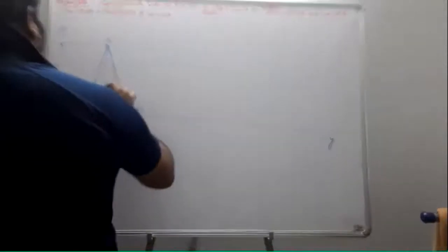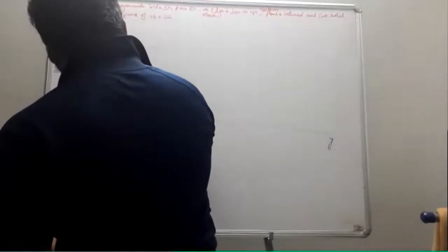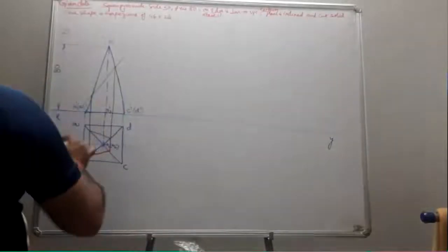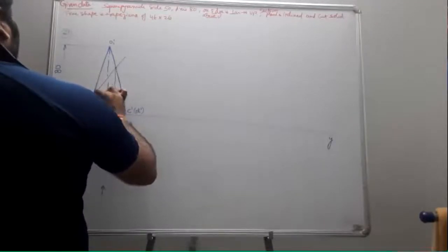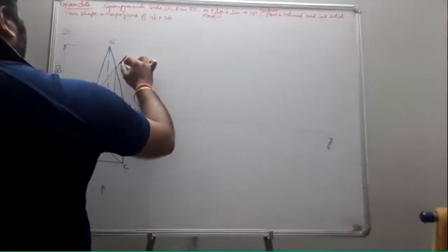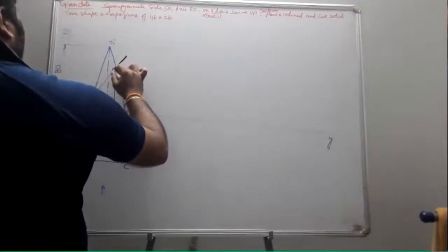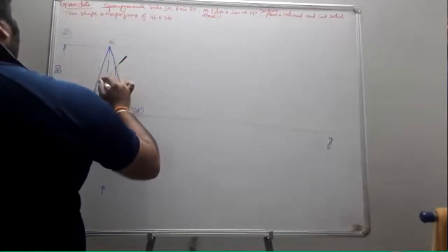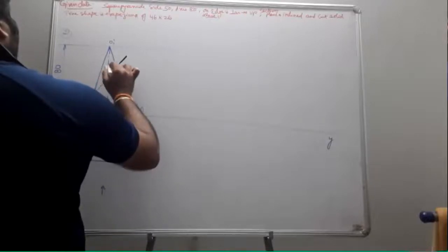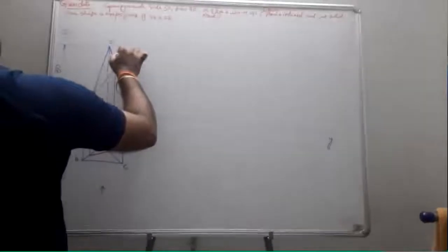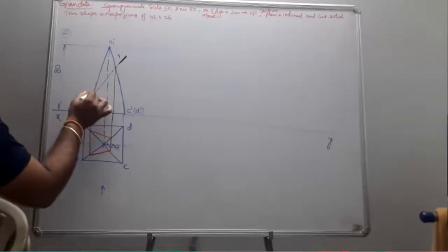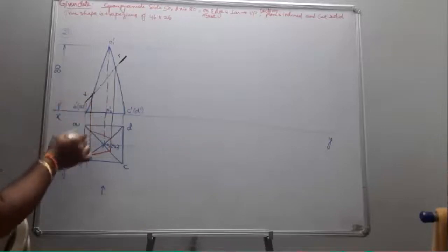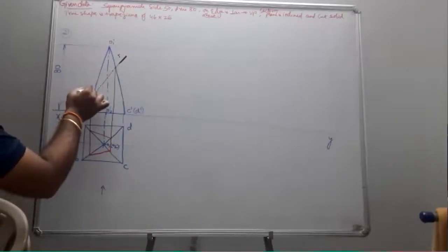Now you just take your section plane in such a way that it is passing in this manner. So this is your vertical trace VT. Okay. Now tell me what are the numbers you are going to see. Always start from extreme left. So OA, that is OB, is going to be visible, which is 1.